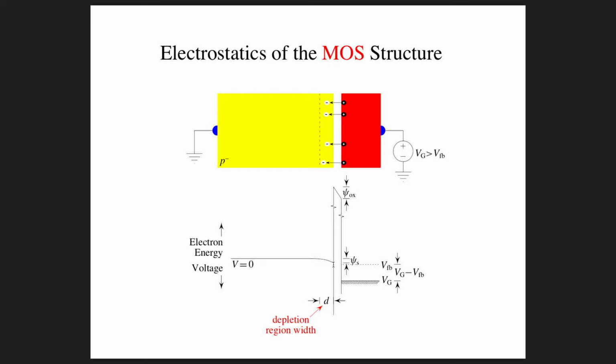And this is a parabolic shape. And so the potential here at the surface, this little minimum value here before we hit the insulator, is called the surface potential, the potential at the surface, which is typically denoted psi sub s, as shown right here.